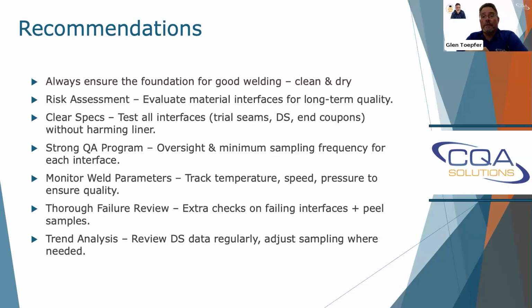But if you have an issue, make sure the installer's pulling end coupons and testing the 1 inch coupons to see if those textured interfaces or smooth textured interfaces are good. Then you can maybe avoid some laboratory samples. There's already going to be a hole there, so you can take advantage of that. There's different strategies you can implement, and I think it's important that something's implemented.